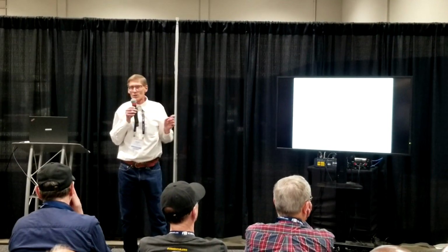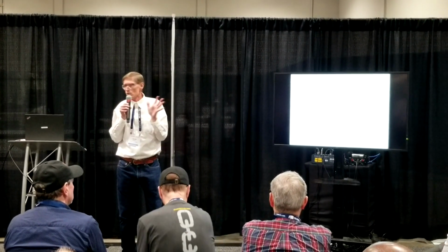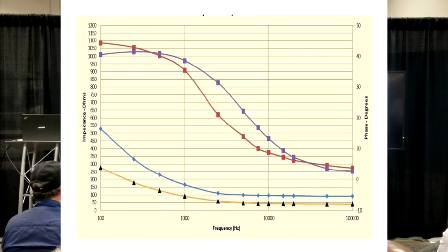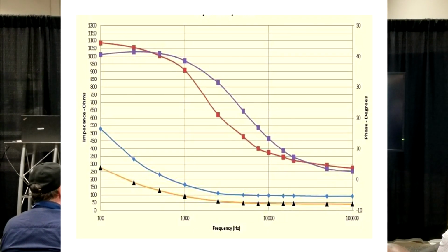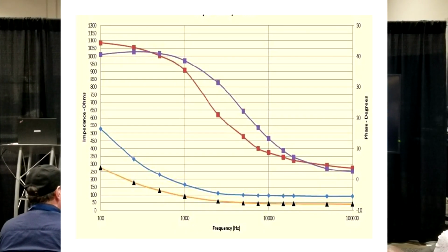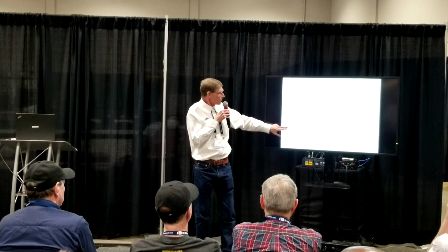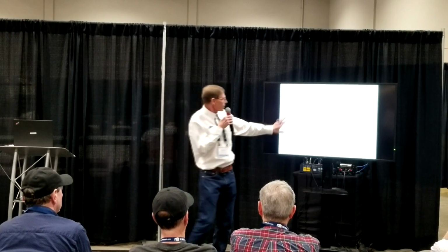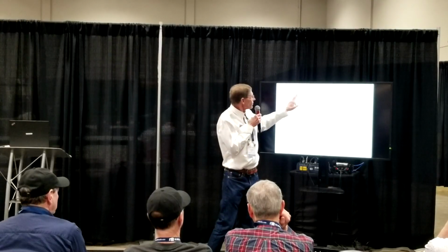Not a perfect one, mind you, because we already saw in the SRL graphs, the pretty blue graphs, that we can't quite do that even though we try. But look at the impedance of the two different designs. This is roughly 525 ohm cable. Damn high. Even at 1,000 hertz, we're at 200 and some ohms. I can make design changes and cable engineers can look at this and say, well, let's improve this. And we got that down to roughly 275 ohms. In other words, roughly half. Now, one thing you'll also notice is look at the difference in the phase.